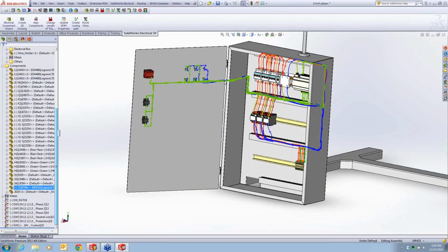Now what you see here is that, for performance reasons, I chose to use just sketches. Let me come back to the routing of wires again. One thing I'll mention before I do this is the colors that you see here are all automatically linked up with what was defined in the 2D tool. So if you remember the red, orange, green, and blue wires, these match up to those red, orange, green, and blue wires that we saw in the 2D sketch tool. Again, I used sketching so that it would render faster.